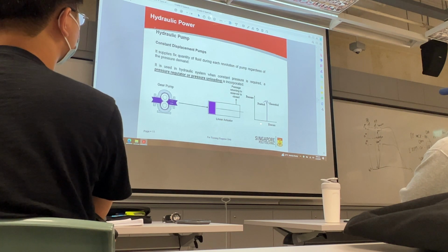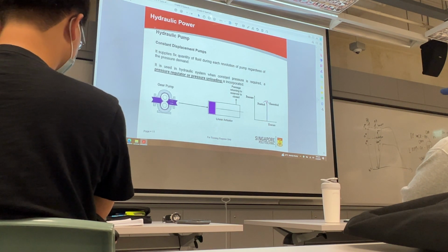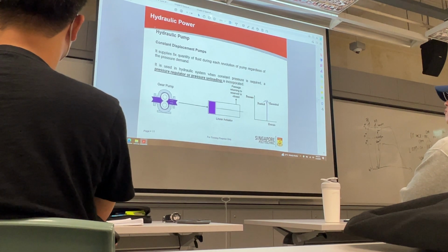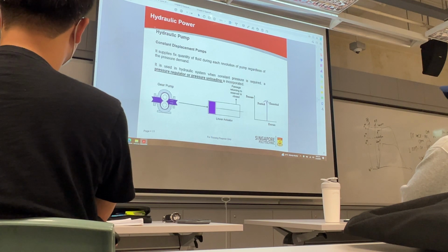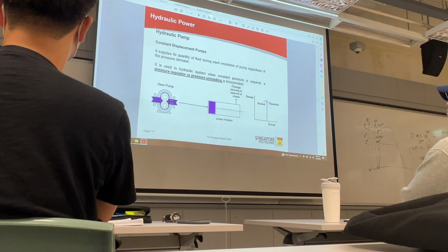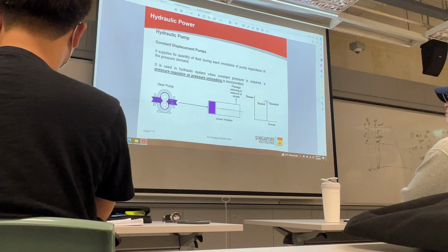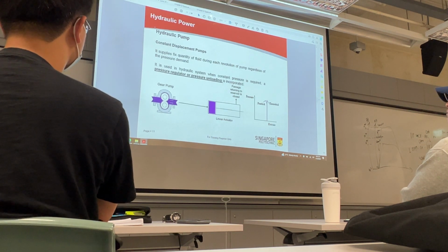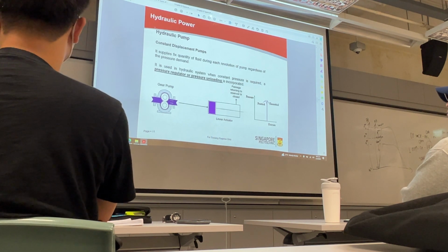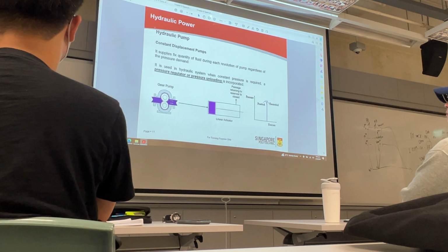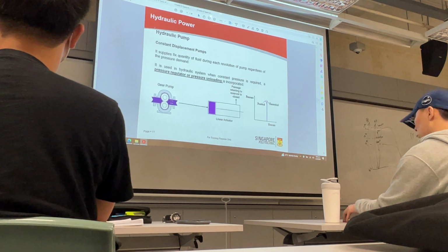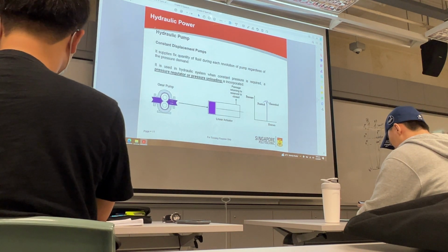If you have resistance, it will build up the pressure and cause an explosion. So in this experiment, what we did was put a relief valve there so that the resistance will build up. However, a relief valve is not supposed to be used to regulate the pressure demand of the actuator. So the only way is actually to install a pressure relief valve. Okay? The pressure relief valve, what is the pressure setting? I just throw one value, 25 plus or minus 5 bar. This is the pressure that is needed in my system.